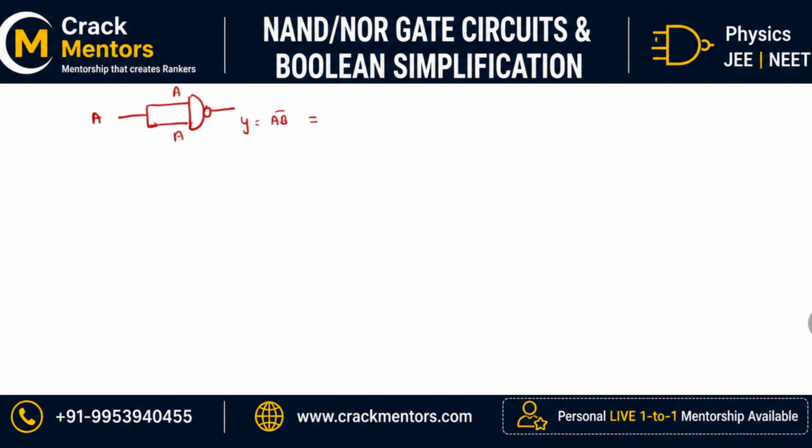Since I know that A and B both are same, can I write that this is equal to A naught plus B naught? Since A is equal to B only, I'll be writing A naught plus A naught, which is equal to A naught only. So here you find that a single input NAND gate is behaving like a NOT gate.